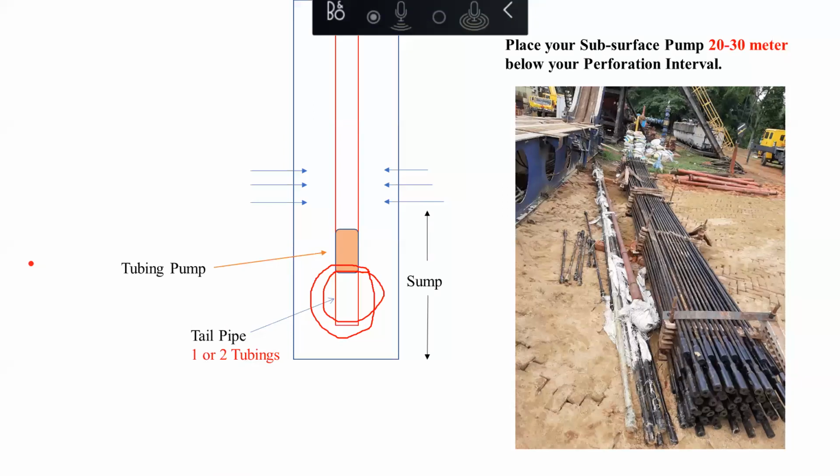If there is a leakage in the tubing, you need to pull out the 10 stands that you have tested earlier. So you pull out the 10 stands and then you test it again. If there is any pressure loss, you remove another 10, and you test it again. If the pressure holds, you add another 10. Likewise, you are going to either remove your tubing as well as adding it.